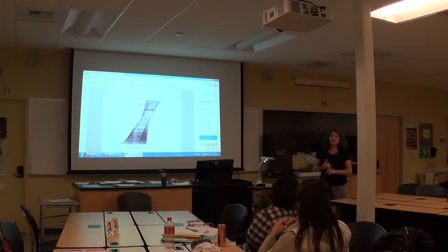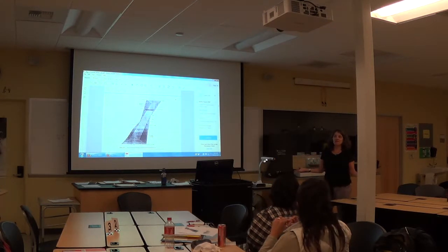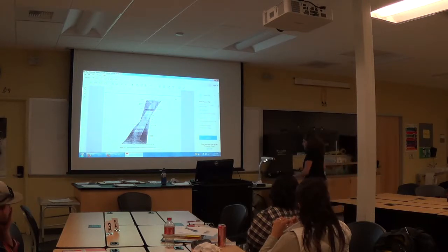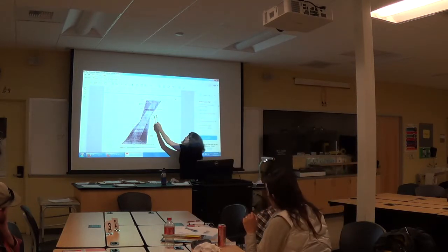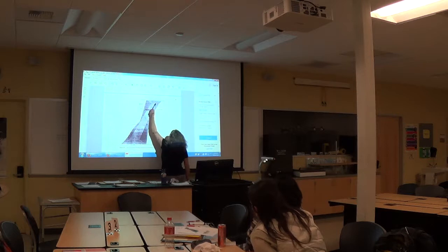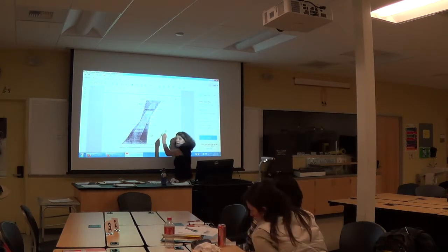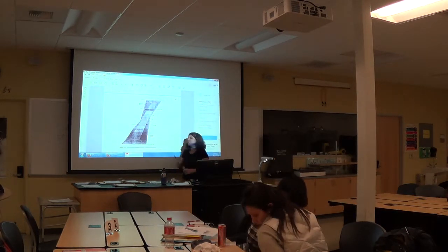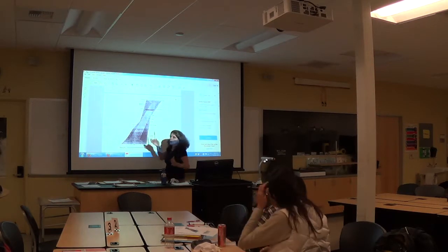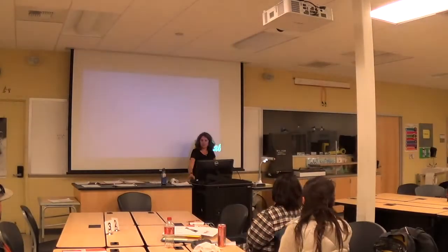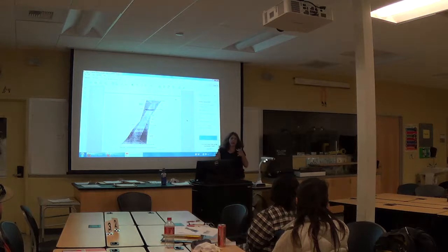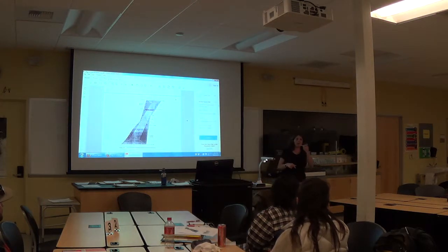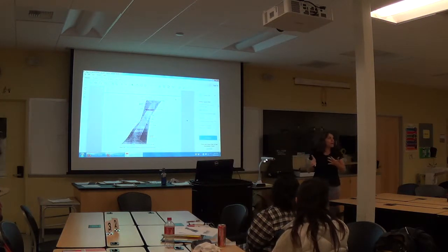What other sophisticated ways do you know in this class to do areas? The double area method. If I know the coordinates of this point, this point, this point, and this point, can I find that area? Right? And then let's take that area and multiply it by a 1 foot width. Then I have a volume, right? If I calculate the area and multiply it by 1 foot, I now have a volume.